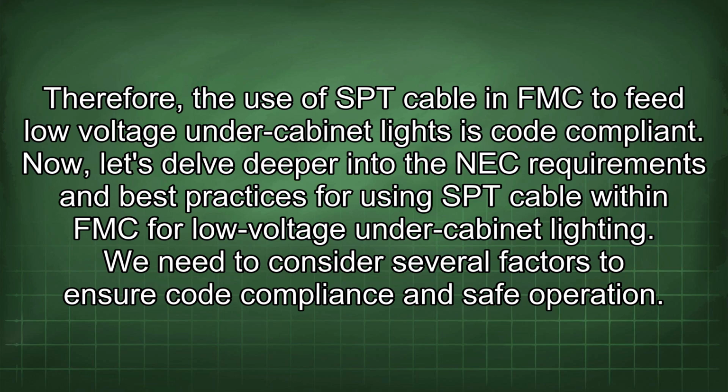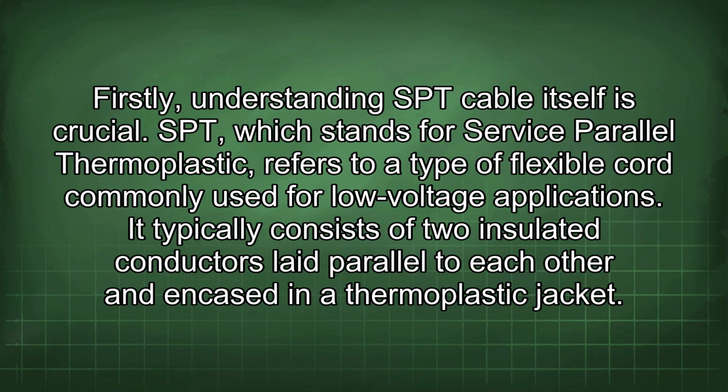Now, let's delve deeper into the NEC requirements and best practices for using SPT cable within FMC for low voltage under-cabinet lighting. We need to consider several factors to ensure code compliance and safe operation. Firstly, understanding SPT cable itself is crucial. SPT, which stands for Service Parallel Thermoplastic, refers to a type of flexible cord commonly used for low voltage applications. It typically consists of two insulated conductors laid parallel to each other and encased in a thermoplastic jacket.